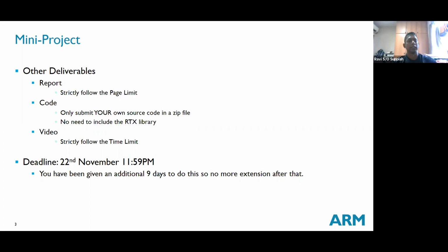Because your stack size within the task is very limited, you need to create global variables for your variables. In that case, it is fine. But the thing you should not do is create global variables to make it the default way in which your tasks communicate with everything, without using message queues or semaphores or anything like that. So that is the restriction behind global variables.